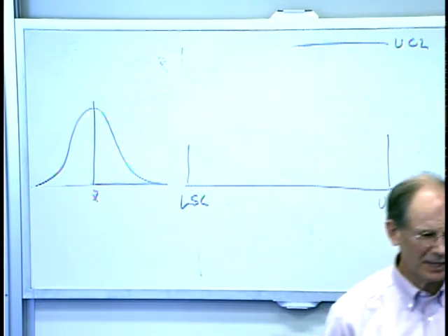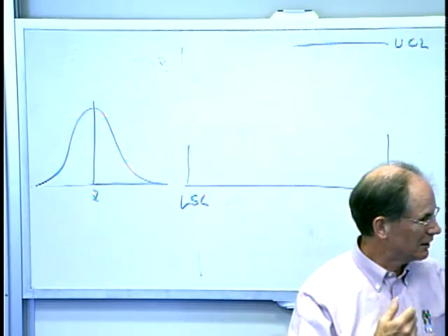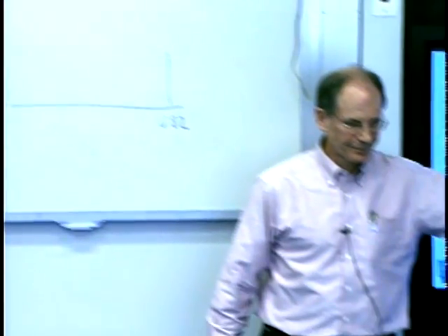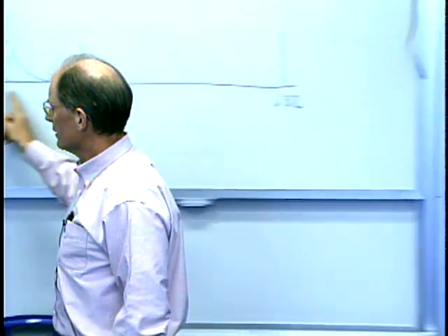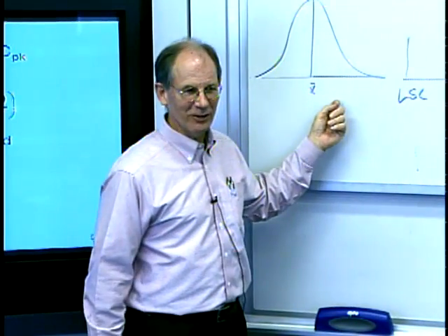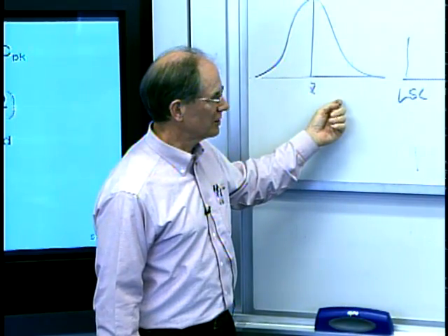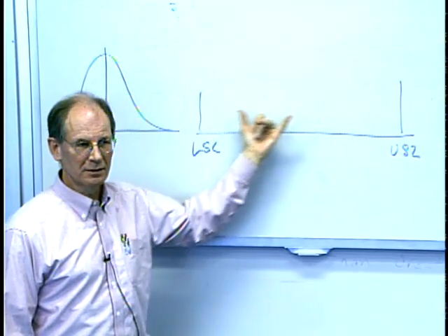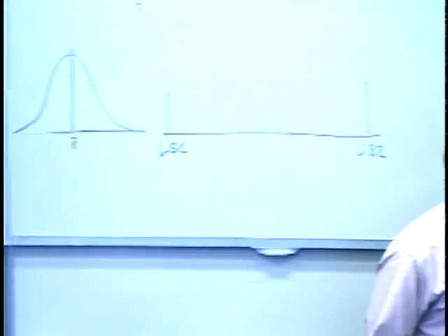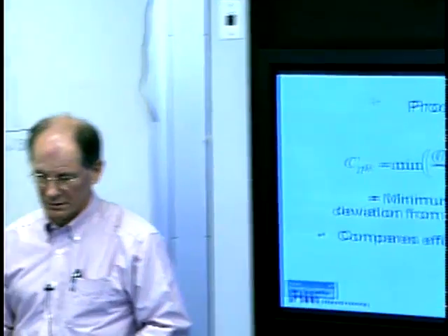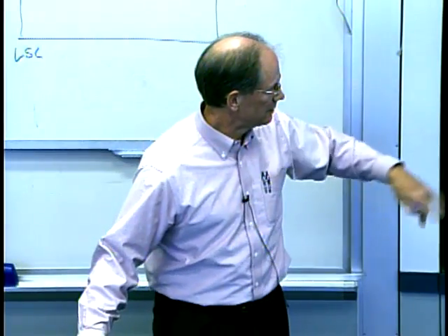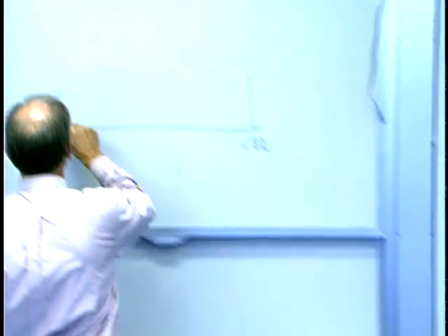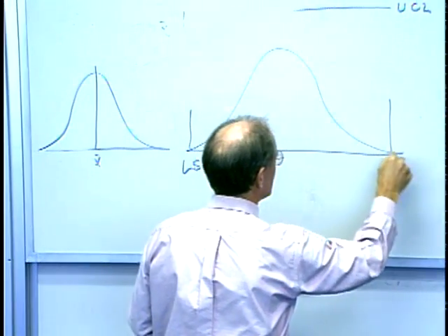So we come up with this CPK measure, and there are a whole pile of these different ways of looking at stuff. CPK now penalizes deviations from the mean. So now this would have either a negative or 0 CPK, and if you do the calculation, this is sort of a blend between how well it's centered in here and what the deviation is. So if it's perfectly centered, then these two numbers... if it's perfectly centered and it exactly fits like this, what's CPK going to be?